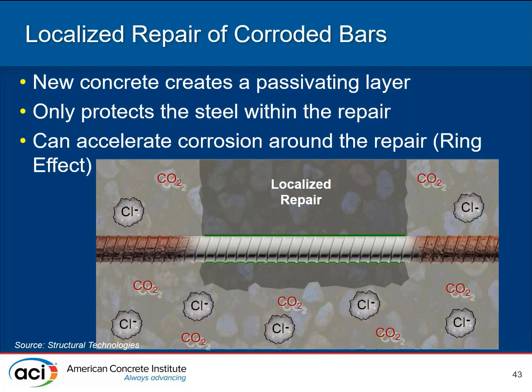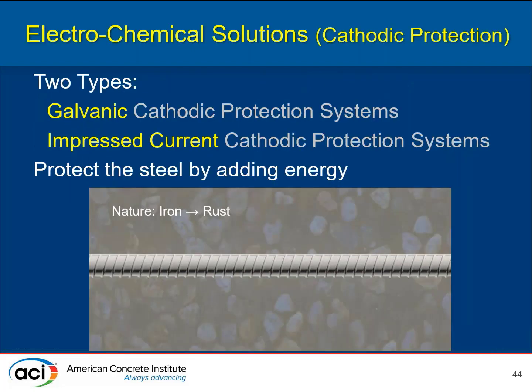This is why that's happening, the ring anode effect. Well, how do we avoid that? You can't avoid it. The right solution isn't to prevent the difference, or to add chlorides into the localized repair and then match everything so nothing's the same, because then you've got a lot of salt going. You really need to think about electrochemical solutions.